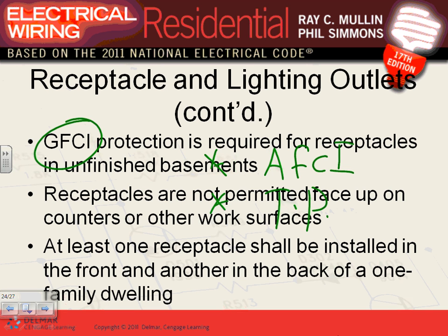The second thing is, if you have receptacles in a wet or damp location, you have to have an in-use cover, outdoor, as well as weatherproof. So outdoor, you're going to have the following: in-use cover. Everybody knows what in-use cover is, and weatherproof. The receptacles that you put outdoor need an in-use cover, a plug-in cover, and weatherproof. Weatherproof will run you a couple of bucks more than non-weatherproof receptacles.